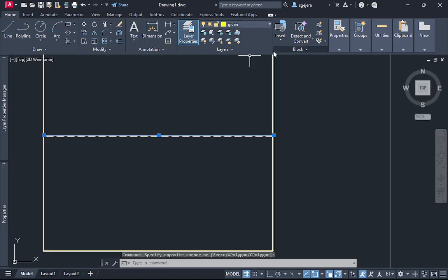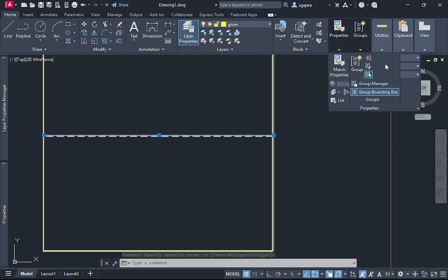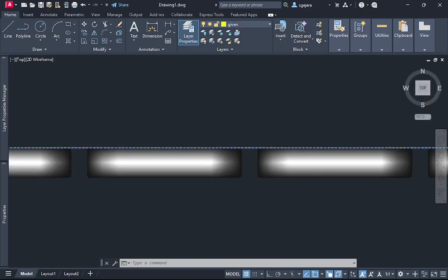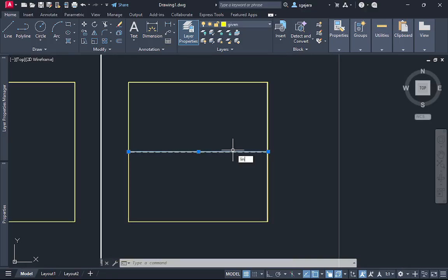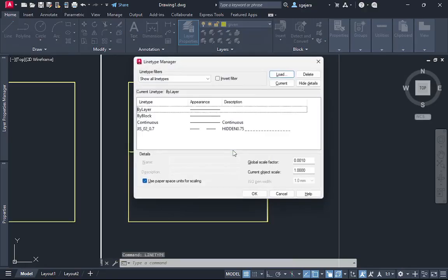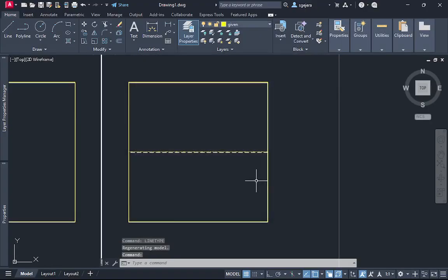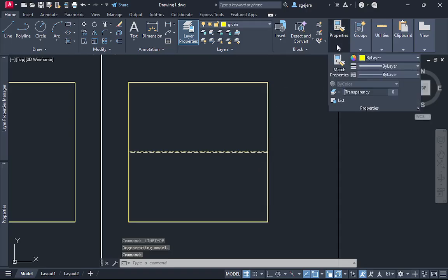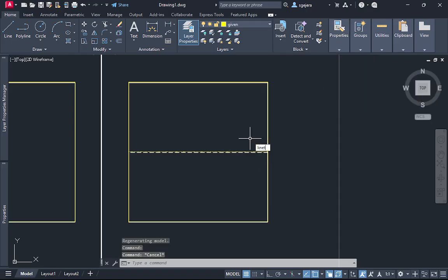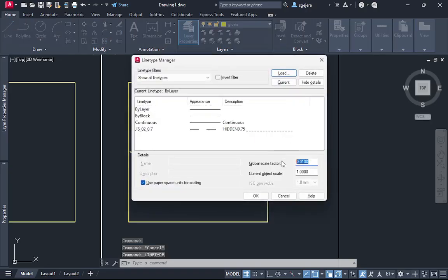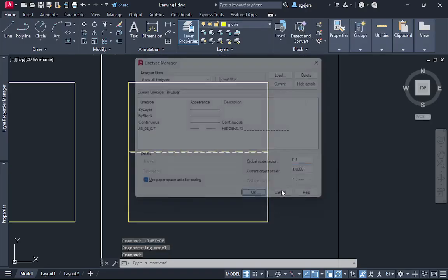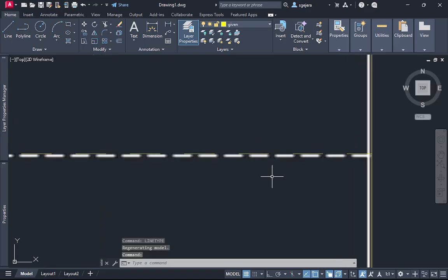Oh, sorry. That's why. I haven't changed this yet. This should be JIS. So, it's already small. So, let's do line type again. I think this was 0.01. 0.01 is too small. So, let's do line type. It looks like 0.1 is appropriate. There, 0.1. 0.1 is good enough.